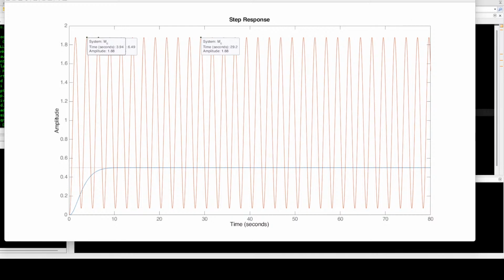So we're going to take those values. KU, the ultimate gain, which is where we hit the oscillations, was 37.44. Our critical gain, which is where we're going to start our tuning, is KC, which is half of that, 37.44 divided by 2, which is 18.72. All right.